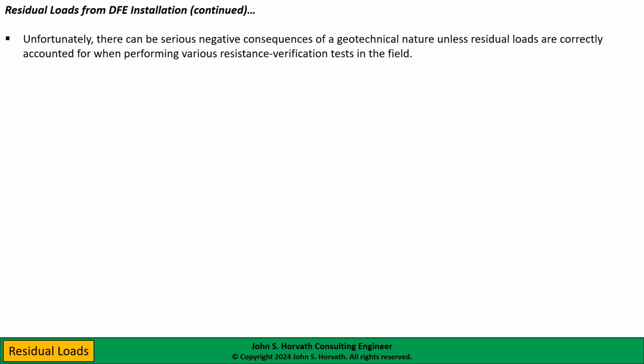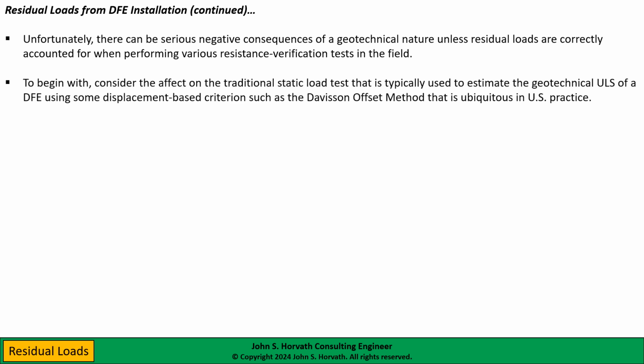Well, we looked at the good news. Let's look at the not so good news. There can be some serious negative consequences of a geotechnical nature unless residual loads are correctly accounted for when you use various resistance verification tests in the field. Let's start off by looking at the traditional static load test that many consider to be the so-called gold standard for measuring the quote-unquote true geotechnical capacity of a deep foundation element.